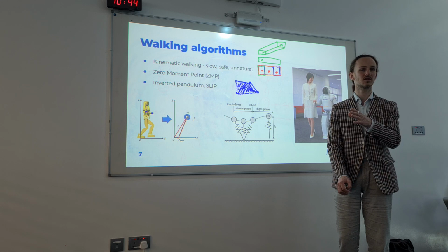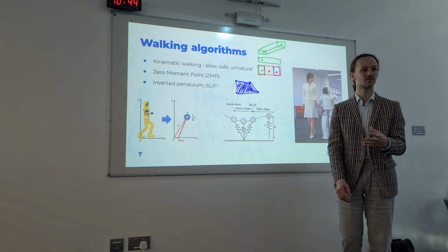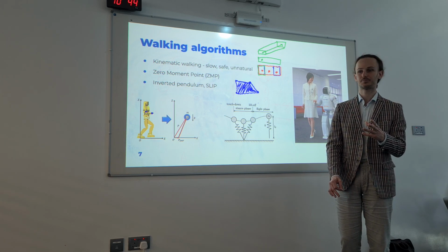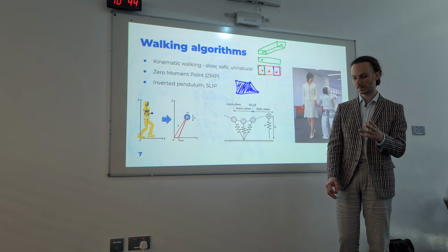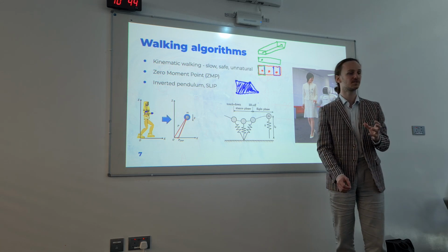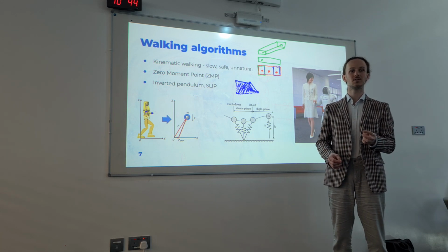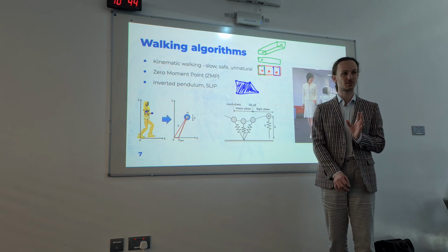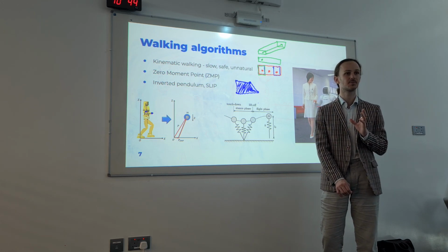So let's suppose you're accelerating somewhere, and if the angular acceleration is exactly zero, the zero moment point is the same as the projection of the center of mass.